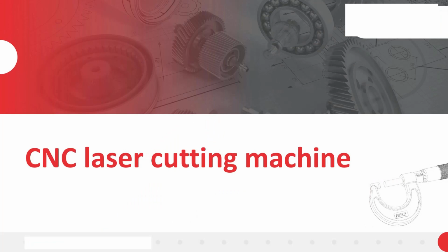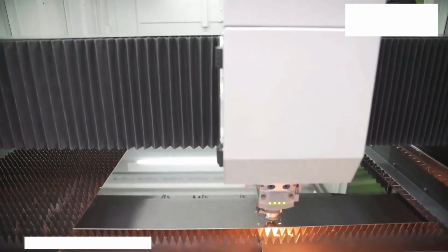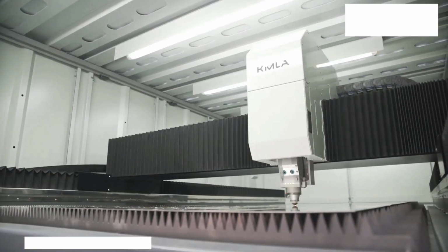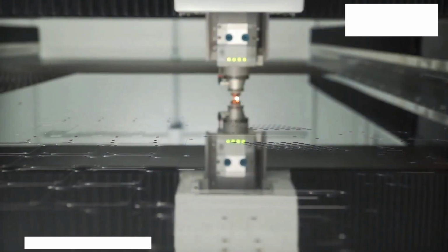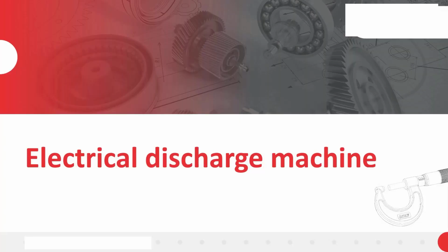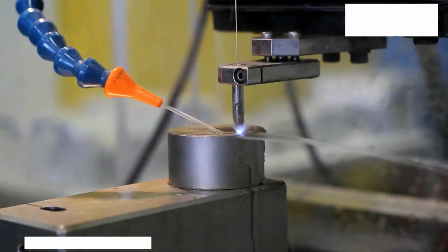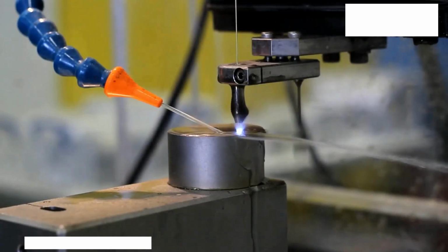CNC laser cutting machine. Laser cutting is a technology that uses a laser to cut materials and is typically used for industrial manufacturing applications. A focused laser beam directed at the material, which then either melts, burns, vaporizes away, or is blown away by a jet of gas, leaving an edge with a high-quality surface finish. Electrical discharge machine. In EDM, power supply controls the electrical discharges and movement of the electrode about the workpiece. During operation, the workpiece is submerged in a bath of dielectric fluid.